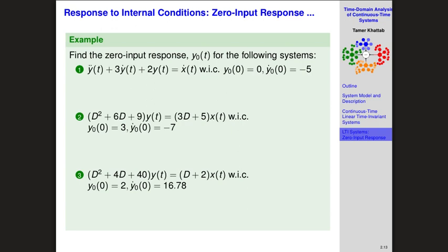So when you have a car with very weak damping, the shock absorbers are not in good condition. You see that if it goes through a bump, it stays oscillating for a while, right? While another car which is in good shape just goes through the bump and absorbs a good amount of the shock, and then it settles very quickly through a damping exponential only, without any oscillation, to its final stable condition. So understanding the behavior of the system without input is very important to know what's going to happen when I put input.